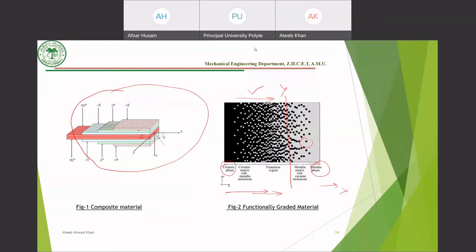So by your argument, if you are saying that it becomes solid or whatever it is, then you cannot call it a composite. Yes, sir, it is purely a composite, you cannot call it a single or homogeneous material. But for design purposes, we are assuming the design concept considers it as a single homogeneous material. Maybe the civil engineers consider it so, as I have a civil engineering background, that's why I'm telling this. You make this assumption for design purposes, but concrete is very much a composite, because a composite is anything made up of two materials which are mixed at different levels, such as the micro level.